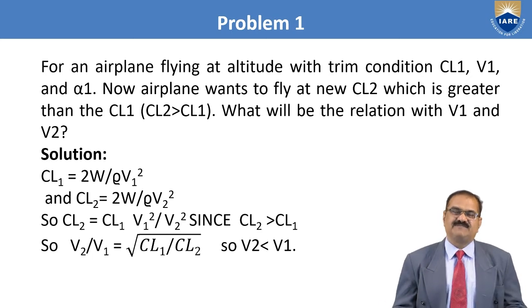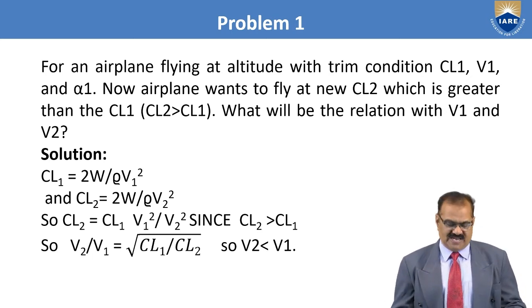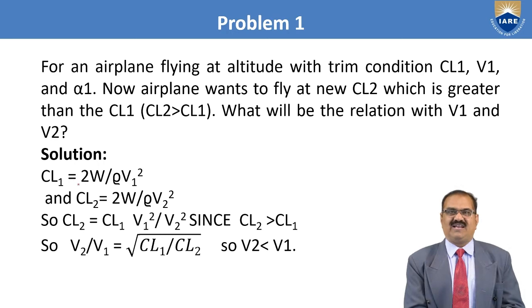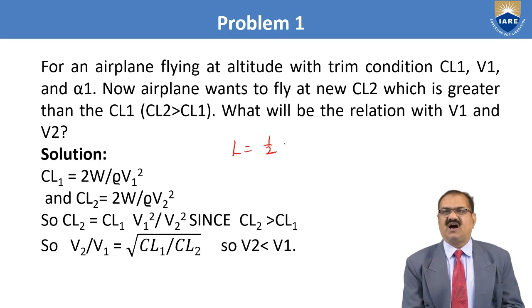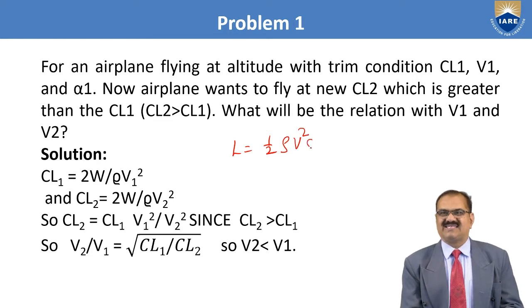We know that for cruise flight, lift is equal to half rho V square S into CL. For the cruise condition, lift is equal to weight.